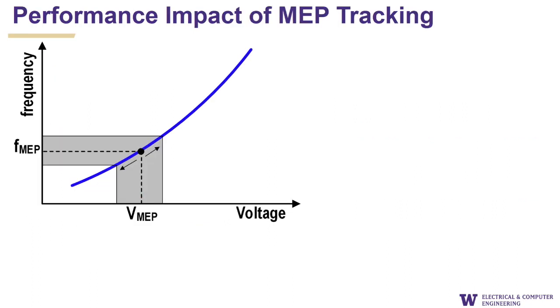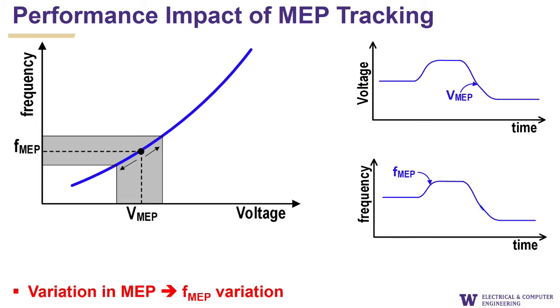That's what we want to go after. So if I dial my minimum energy point, as a necessary consequence, when I start playing with the voltage my circuits are running at, the frequency at which they'll run, naturally, is updated. So I'm going to have different frequencies that I'm going to be running the system at if I want to hunt for minimum energy. Here's a catch.